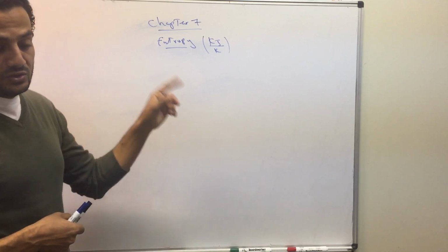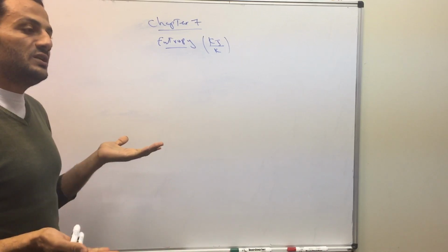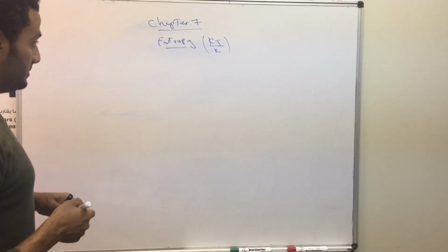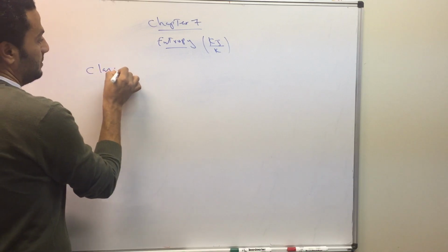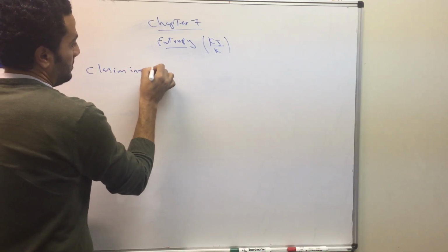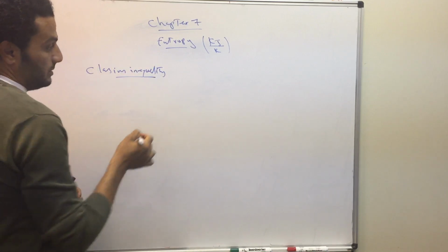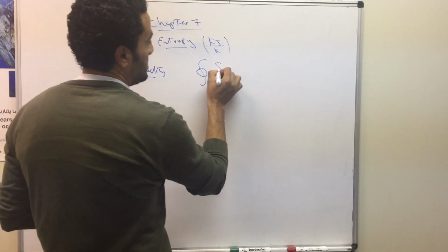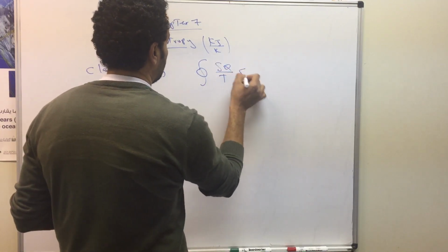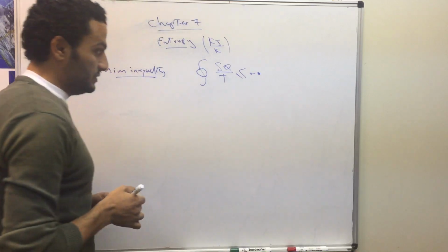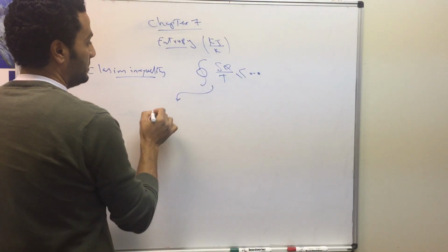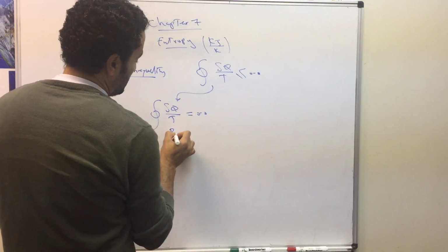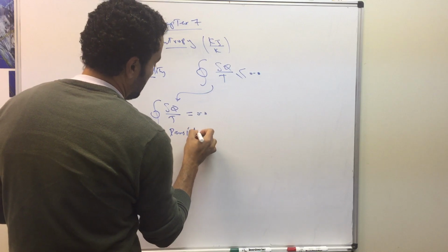As the amount of entropy generated within the system increases, this means the system contains a higher amount of losses. By the way, based on the Clausius inequality, we can prove, in relation to the second law of thermodynamics, that the integration over the cycle of delta Q over T, where delta Q is the heat transfer, should be less than or equal to 0. This term can be reduced to equal 0 in the case when we have a reversible cycle.